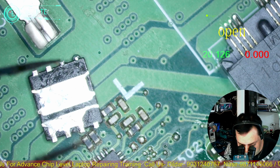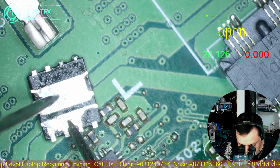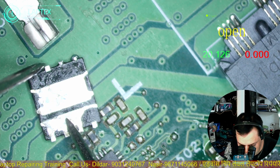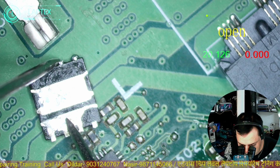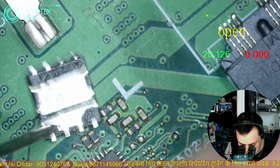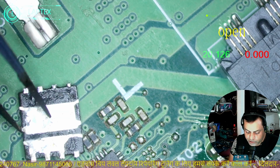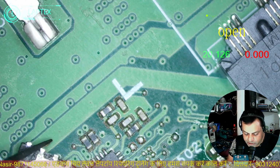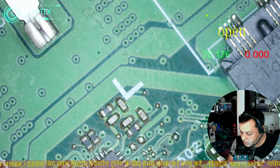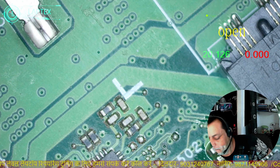So I am keeping it here to check whether I need to replace it or not. No shorting at all. It is very good that my MOSFET is safe, so I will put it back later on. I am going to find the shorting. The easiest and very common method is that you put a jumper wire on this area.